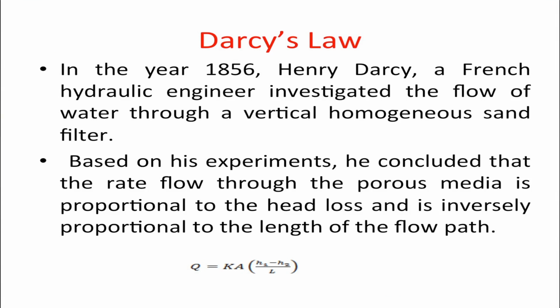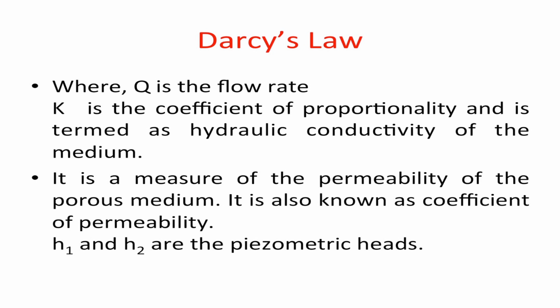V is proportional to I. I is nothing but the ratio between the head loss, the difference in piezometric head H1 minus H2, divided by the length of flow. Coming to the rate of flow, Q equal to K into A into I.